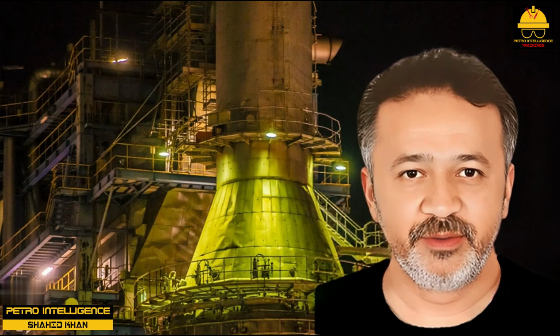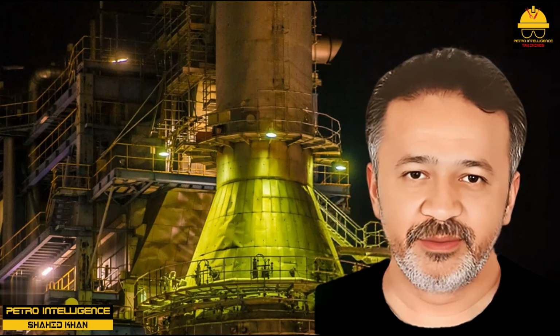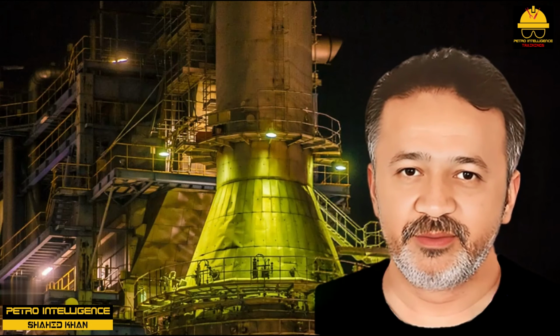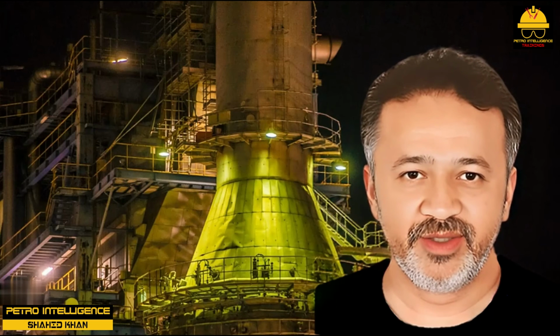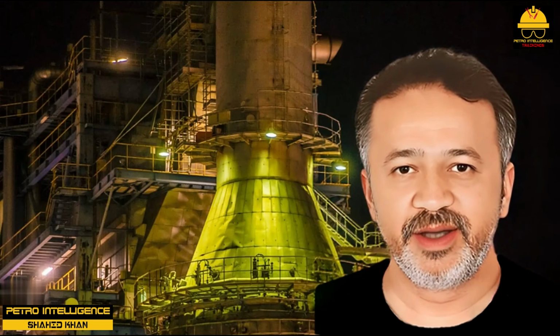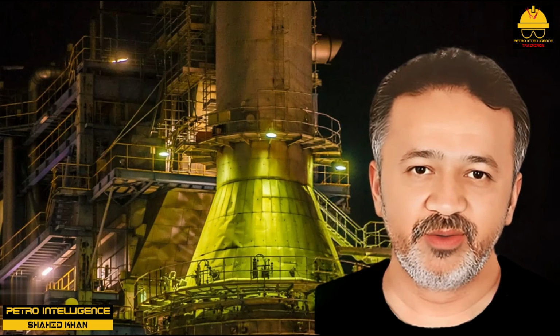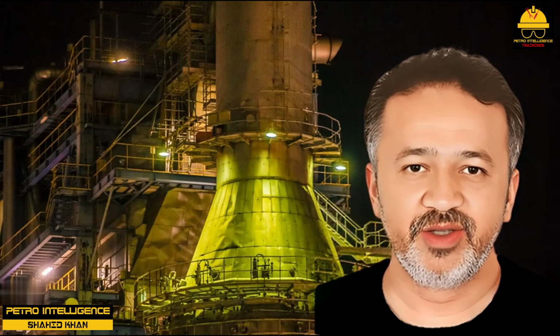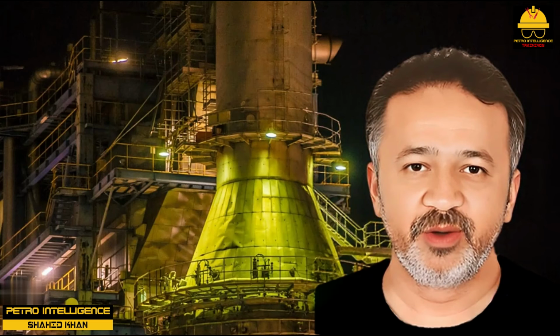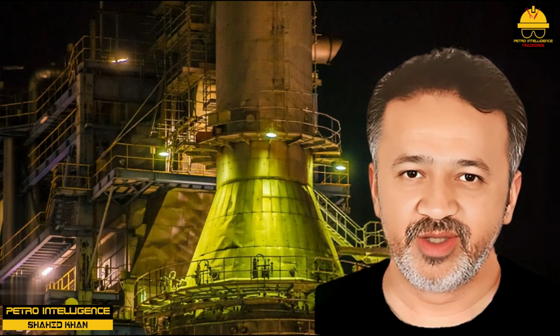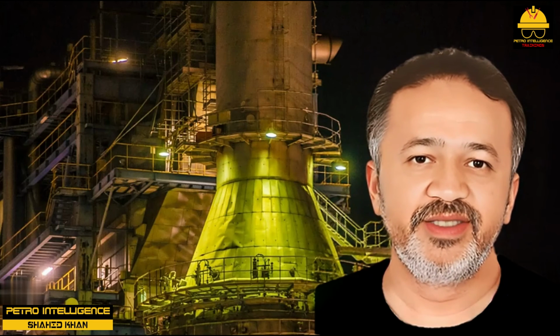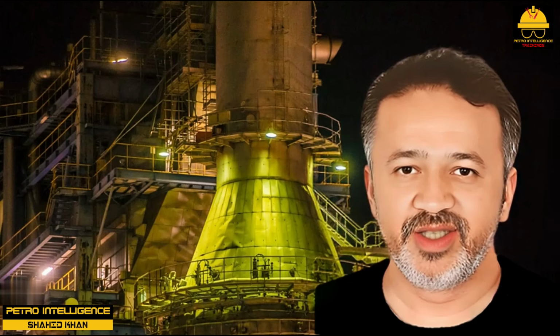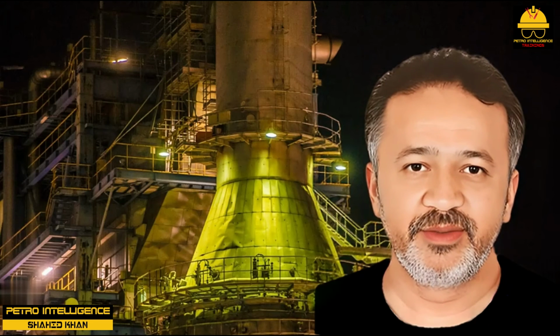Vibrations in fired equipment and afterburn. Balanced draft or induced draft furnaces and boilers are intended to be operated with a small negative pressure, about 0.1 inch H2O, just below the first row of convective tubes, that is, just below the shock tubes. If we operate such a piece of equipment with a severe shortage of air in the firebox and massive air leakage in the convective section, it may sometimes experience thumping, puffing, or vibration.